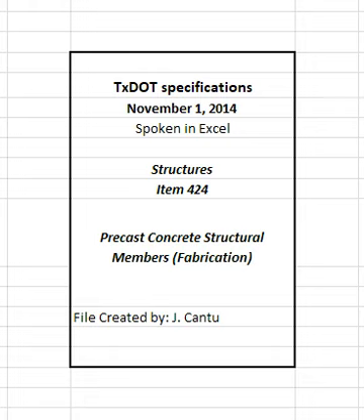Keep exposed concrete surfaces continuously wet for the duration of the specified curing period, unless an approved liquid membrane-forming curing compound is used. Membrane curing compound is only permitted as noted in this section or in the pertinent item. Approved equipment and materials for curing must be on-site and available for immediate use before placing concrete. Provide temperature probes to monitor the concrete temperature or curing enclosure air temperature as specified in Table 2.